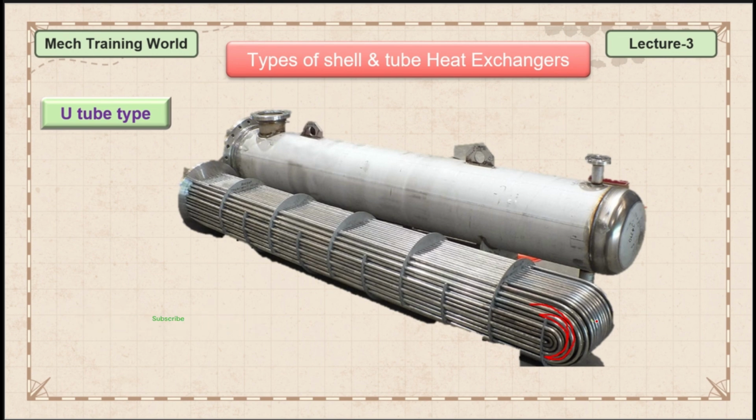But here the main problem is maintenance. So the setup is inside the tube, right? The whole setup is inside the tube. So it is difficult to clean mechanically. So mechanical maintenance is difficult, but you can clean by using a pressurized fluid, guys. You can inject pressurized fluid in these tubes and you can clean it. But mechanically, it is not possible.